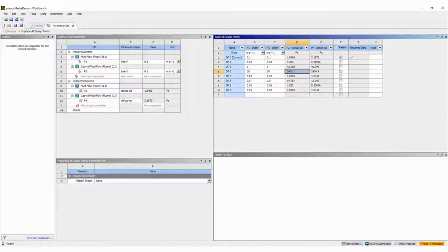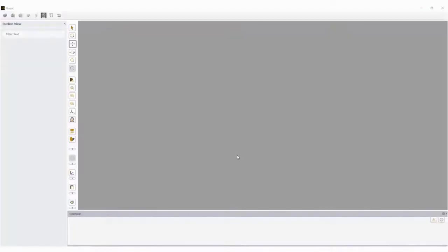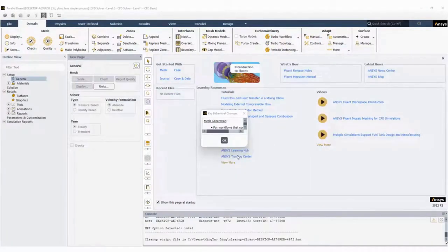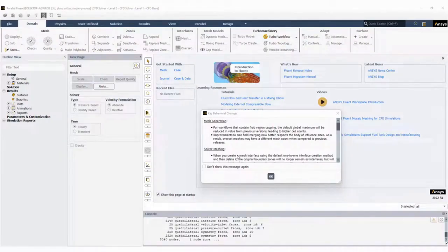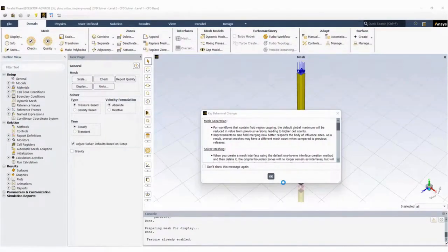approach. As you can see in the Ansys Fluent window, there are many other options and parameters available for porous media. You can do additional corrections to try to span greater ranges and make sure that the results are accurate, so that we have additional options, more advanced models for porous media as needed. But this basic type of calibration can be done very efficiently, very quickly using Ansys CFD.